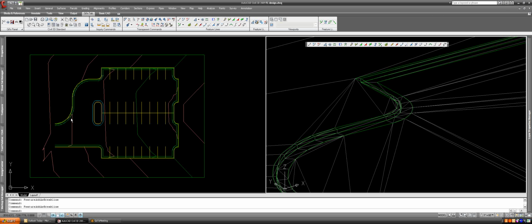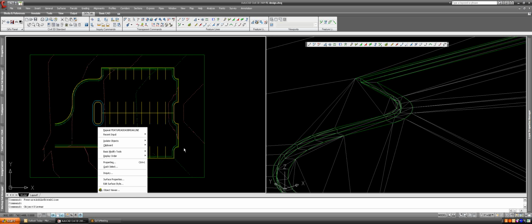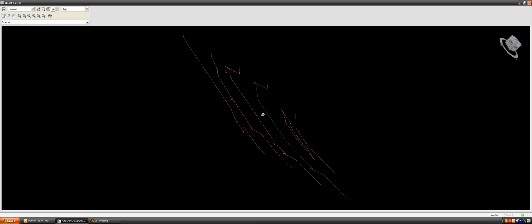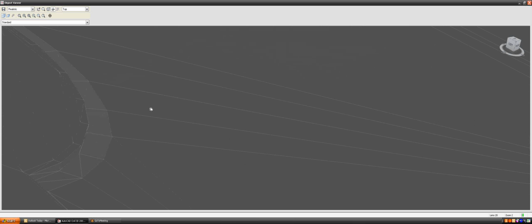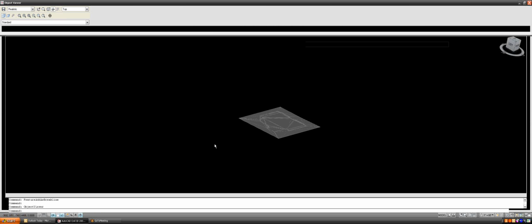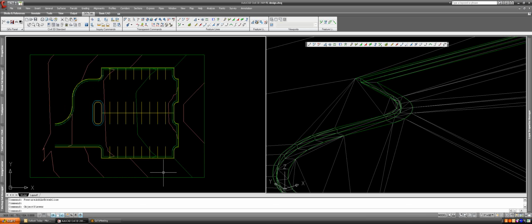Now if you look, we actually graded this whole entire site. Select your object. We're going to 3D view this so we can see it. And if you look, now our surface has a top of curb going down 0.5, and a gutter along with all the grading inside that parking lot. Beautiful. Since this is a temporary surface, you actually want to take the grading out to the existing surface. I'm going to show you real quick grading tools on how to do that and to create a surface really quickly.